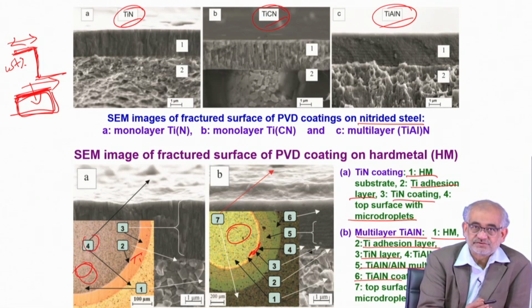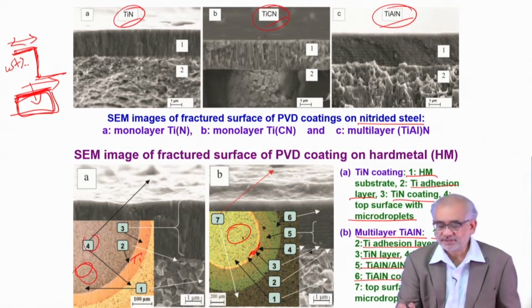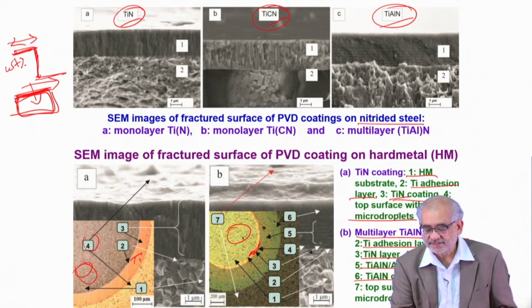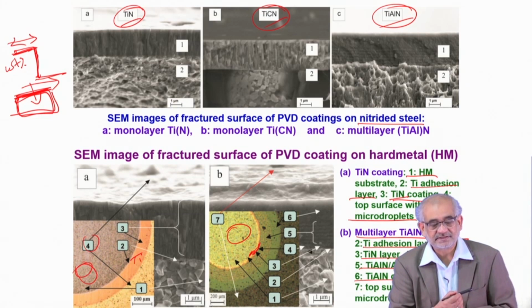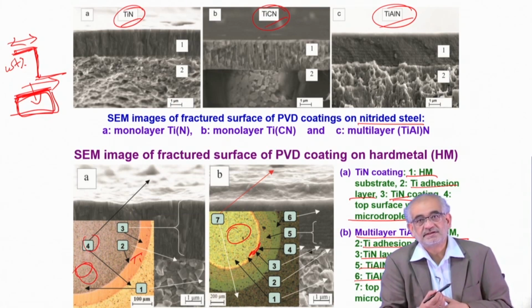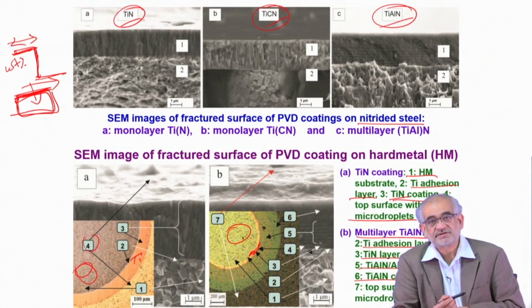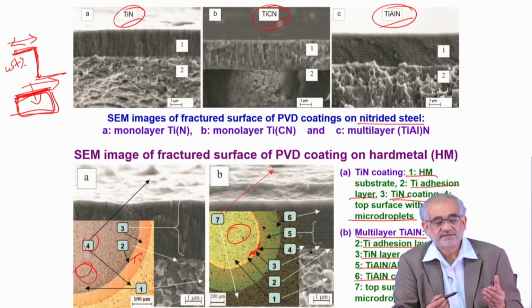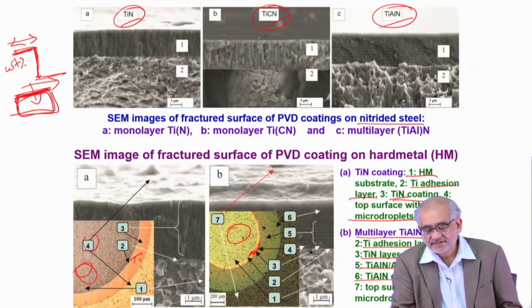which can lead to decohesion during use. On the other hand, if you want a very exotic coating like titanium nitride or titanium aluminum nitride on top of a nitrided steel or some other cutting tool, you don't need a very high thickness coating. You would rather not have a very thick coating, because the mismatch will be substantial, and this can actually lead to complete decohesion. But this is the only way you can have such exotic coatings created on top of a substrate.